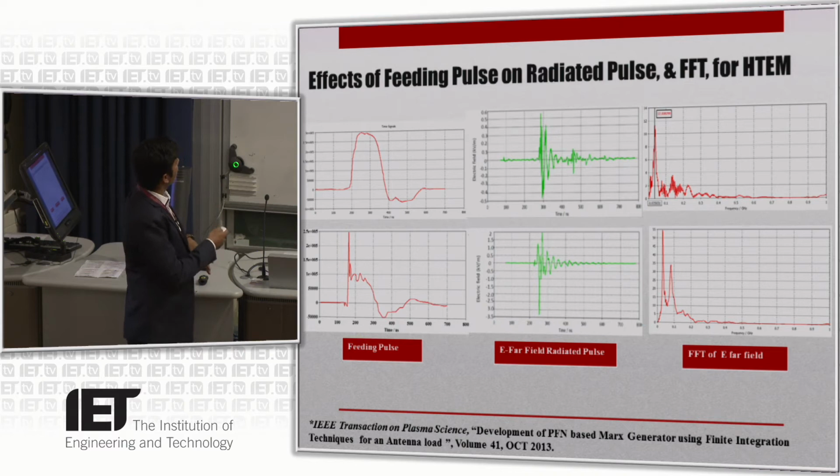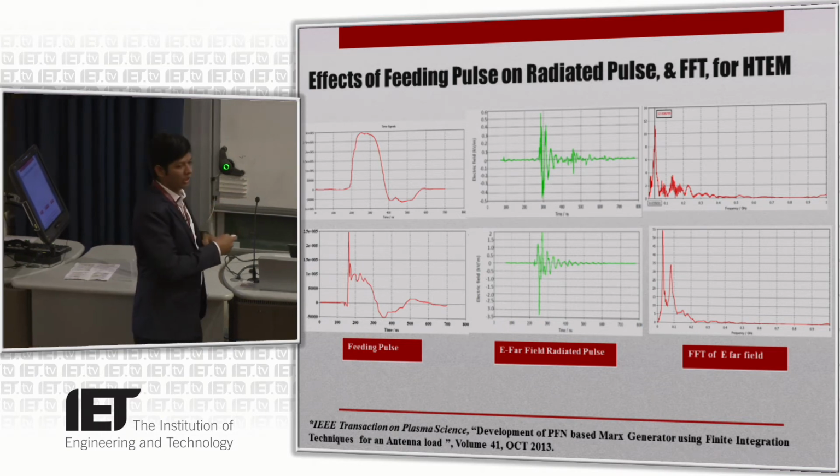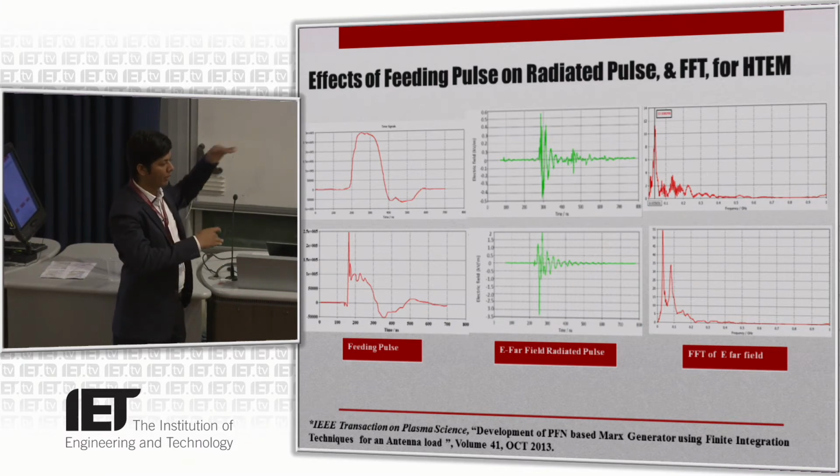Now this is the pulse without the peaking stage. When a capacitor is discharged, there is no peaking. After putting in a peaking stage, the rise time gets sharp, and the amplitude is very high, about 264 kV, and the pulse duration is 300 nanoseconds because the capacitor tank is about 1.5 meters high, and that's why the pulse has that duration. By using a peaking stage, we improved the electric field intensity to 3.5 kV, which was 0.5 kV when the peaking stage is not there.